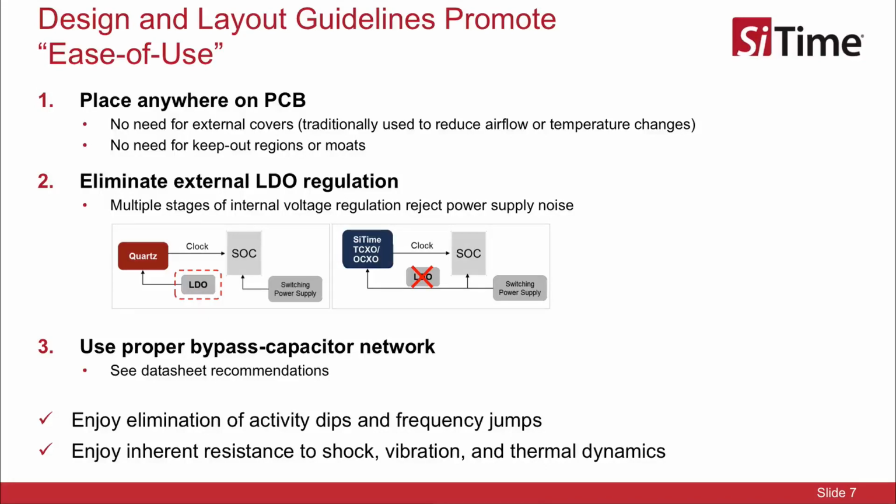Designing with MEMS-based precision oscillators is much easier than with quartz devices. This is because SiTime's devices can be placed anywhere on a PCB, including next to fans that cycle on and off, or next to high-powered devices that radiate a lot of heat. There is no need to shield SiTime's precision oscillators from airflow or thermal gradients using a metal or plastic cover, as required for quartz devices.